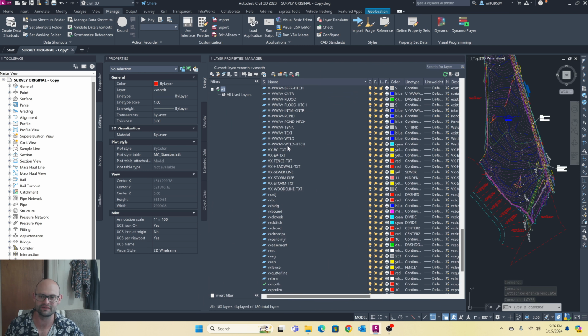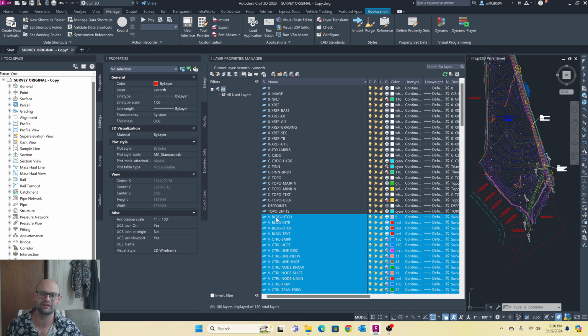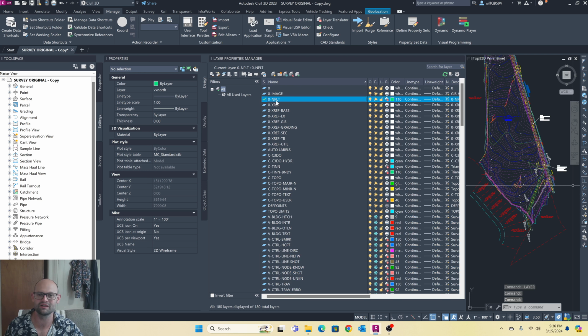Those are R layers. And I'm going to make this a methodical change. I select all of our layers, I click on the bottom one, hold shift and click the top here. And then I'm going to hit freeze. That way, as we move objects off of their layers and onto ours, they disappear from view. It's just like having a checklist. We'll make this the current layer.